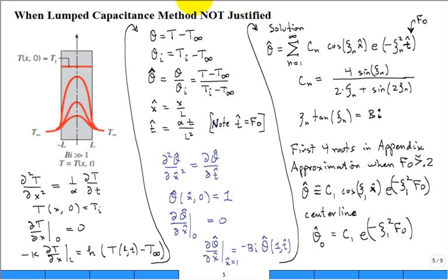So let's do this. We start with this differential equation. True? What is this? Initial condition, boundary condition. I have to have one initial, two boundary conditions. I then introduce theta to help tidy up the math, to make the equations a little more compactly written. I then use theta hat. The book likes theta star, but theta has units of degrees C. Theta hat is truly dimensionless. So we like to move into this generalized representation of the equation.